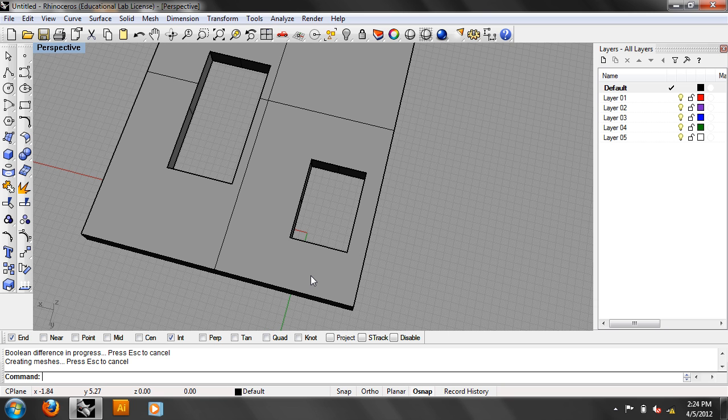You know, and they do that. And you're like, okay, Nick, what's wrong with that? What's the big problem with that? Well, again, that's more operations than the thing that we did. And as your building gets more complicated, like if you have 100 windows, then it really becomes a problem. It's easier just to extrude it than it is to do that.